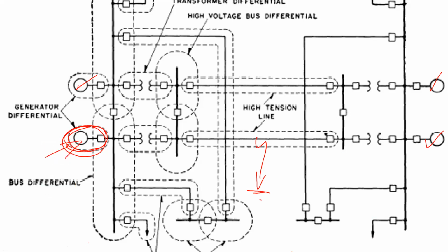But remember, we're saying that in that whole power network, one of the issues that can impact your generator is overload. So if you ask the generator to go beyond its capacity, instead of doing so, which will be detrimental to its operation, it will pull out of synchronism. And obviously, if the generators pull out, the system collapses because there's no supply. So that is all that happened.